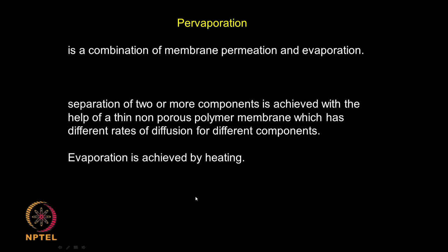The next membrane based technique is pervaporation. This uses a pervaporation membrane. It is a combination of permeation and evaporation, that is why it is called pervaporation. So, the solution is initially evaporated by applying some heat as well as a high vacuum, and then the solute molecules permeate or diffuse through the membrane